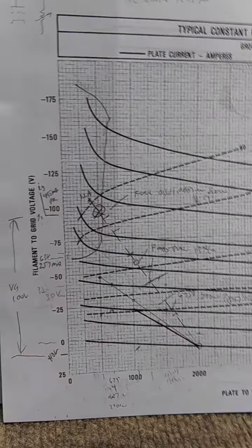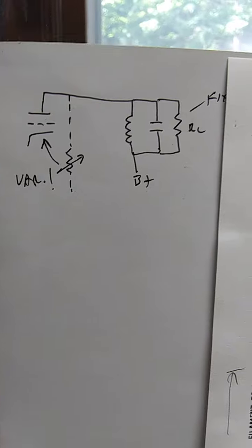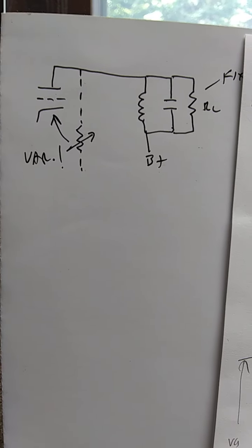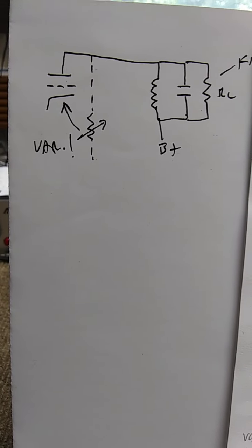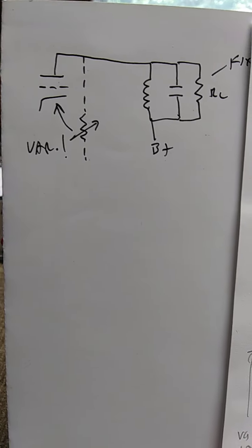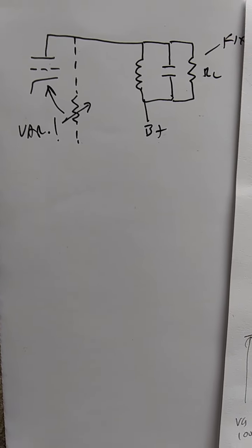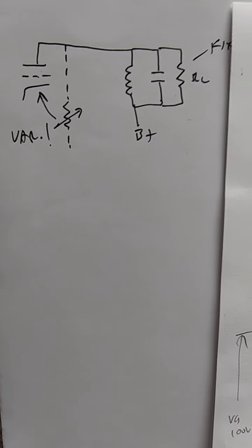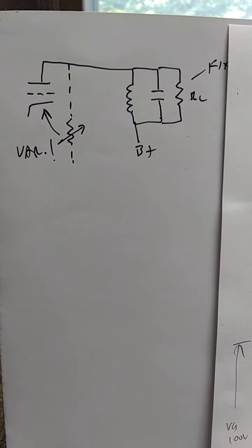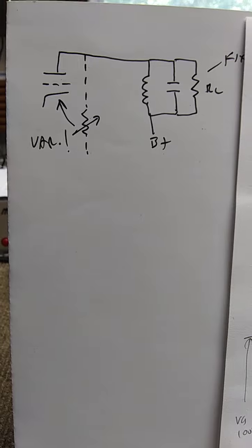Terman says, not about the amplifier, not about the tube, but in the case of the real amps that we're going to build, in the case of the output network, which is usually a pi network, it absolutely must have a fixed value of resistance on the input to the network and the output. And if it doesn't, it will not work. It is a fixed transform. A pi network is a transformer. And if you read earlier in Radio Engineer's Handbook in the Transformer section, you'll find that.